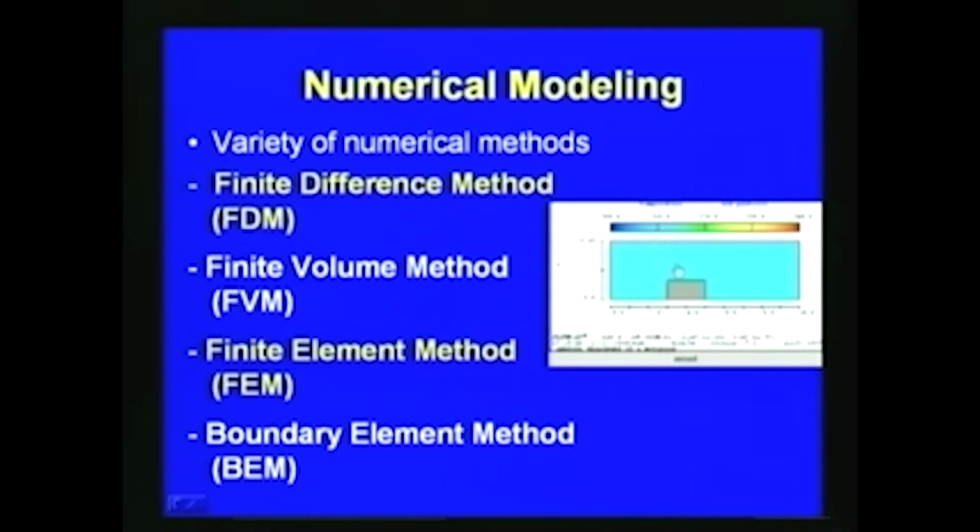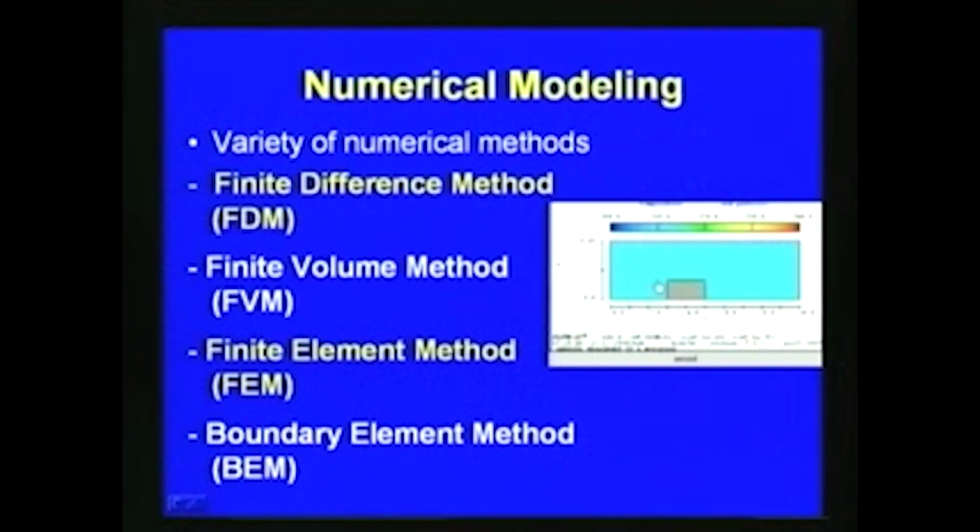Say, for example, if you want to simulate the flow behavior or flow surrounding a cube, we will choose one of these methodologies and discretize this domain. Then we can approximate the Navier-Stokes equations, and as we have already seen, the partial differential equations will be transformed into an algebraic set of equations.